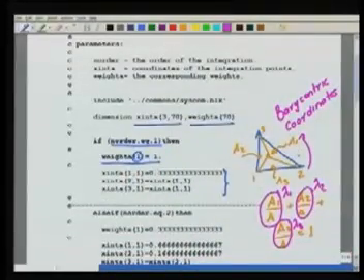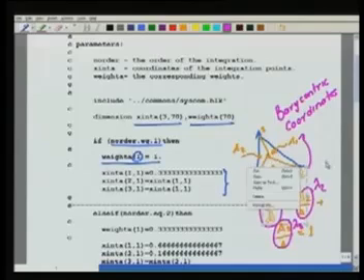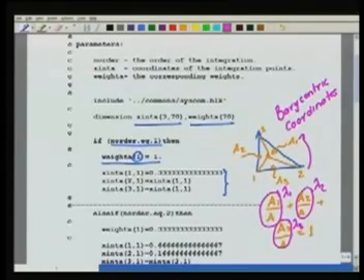It turns out that if you look at lambda 2, lambda 2 is 0 when I have a point on this edge, and it is 1 when I have the point here. Okay, when the point is here, then lambda 2 is 1. Now, which of our psi's and etas is 1 here, 0 here?